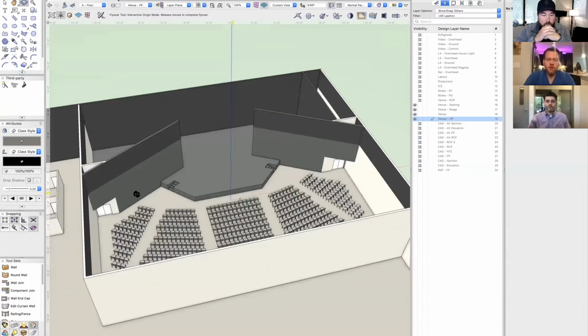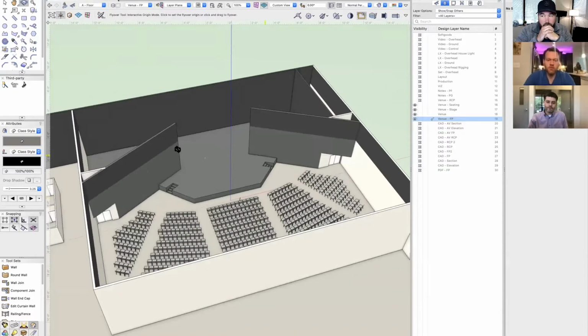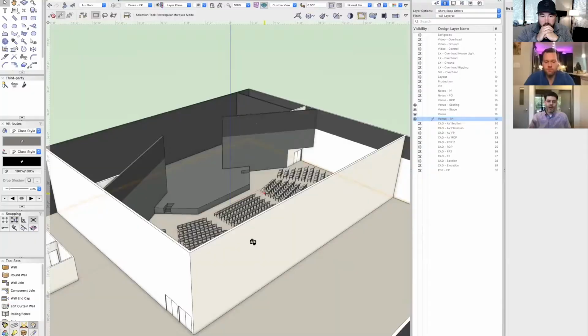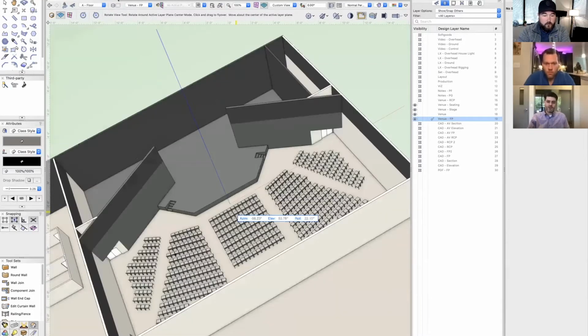So Peter, with something like this, what would you start with for screens? I'm guessing a screen on each wall probably, as we normally see in spaces like this. Yeah. So as I look at the room, there is a formula. The first thing I'm going to want to know is how far away the furthest chair or furthest view is, or where that person is sitting in relationship to the screen. And we get a measurement from that.